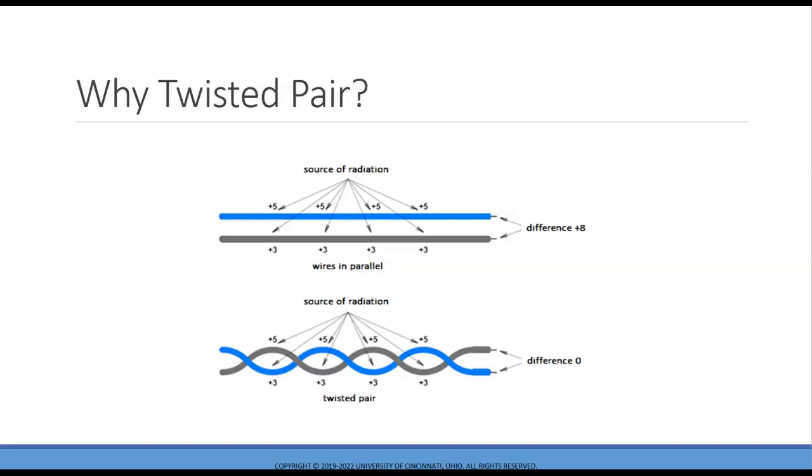This basic concept takes advantage of EMI being stronger the closer in proximity you are to the source. If the 2 wires take turns being closest to the EMI source, they will each absorb an equal amount of interference. In other words, the EMI affected both wires identically. In balanced pair operation, the 2 wires carry equal and opposite complementary signals, and the destination device detects the difference between the 2. This is known as differential mode transmission.